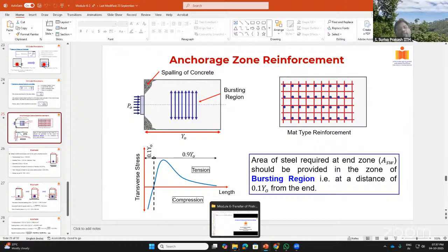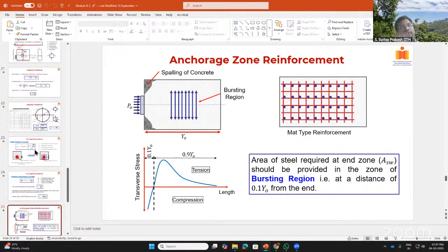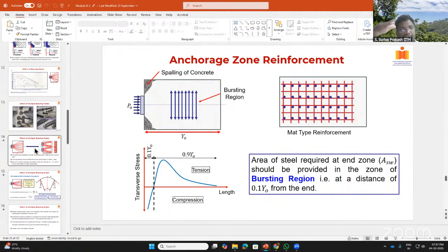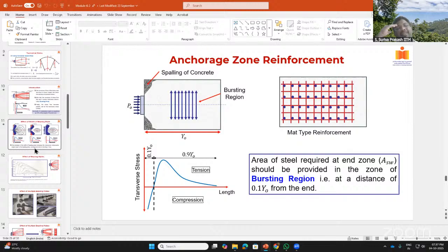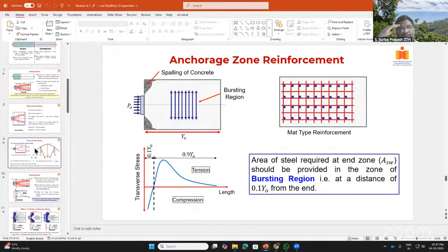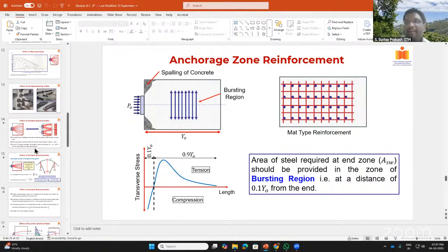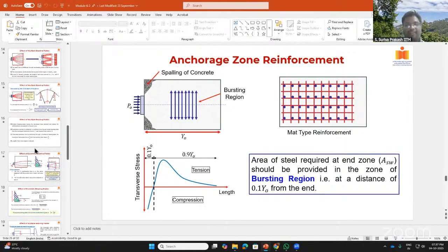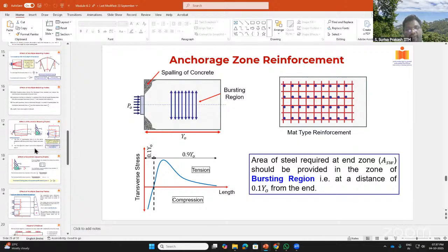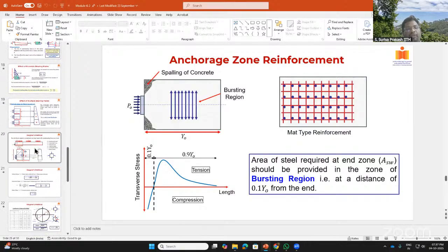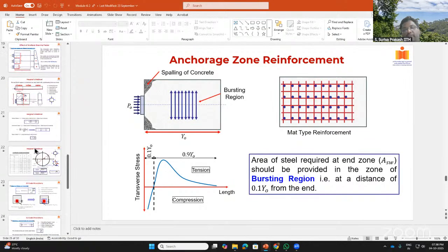See, this is another thing. This usually happens at the end zones, right? Unless you have a lot of rigidity from the supporting element, basically it is going to act like a simply supported connection. If the column size or stiffness is more near the dead end, then only in this case we have to check. Unless your support conditions are different and you have a cantilever slab and then you are terminating somewhere close to that column, then you will have issues. But that's why I said I'm not sure. We have to check and come back to you. That's a good question.